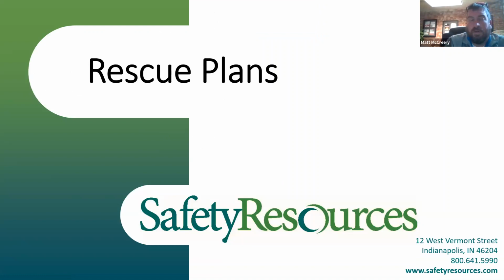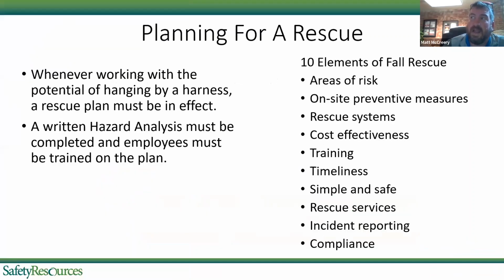So again, we're still going to talk about the steep slope first man up. I think it's the best practice. Make sure that you have a policy on the first man up rule. How do you implement that? And then another thing that I think is forgotten but is required is a rescue plan. Let's say someone gets seriously hurt and you weren't able to rescue them. Not having a rescue plan would be a serious issue.